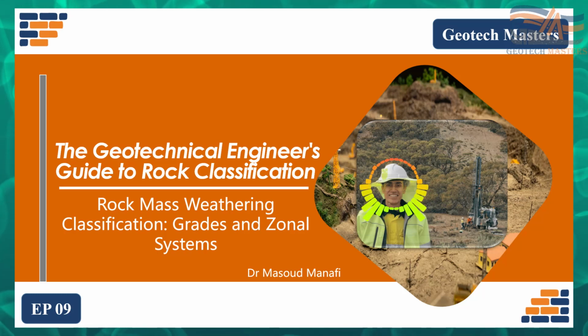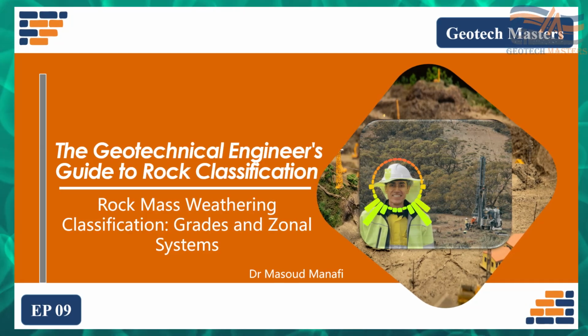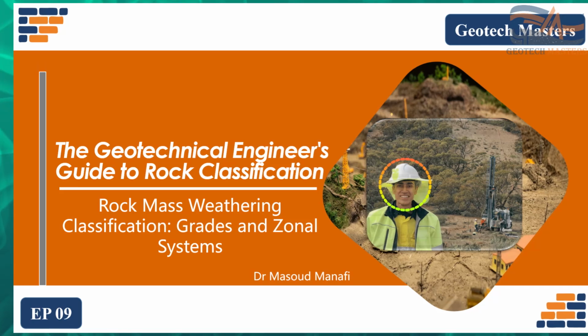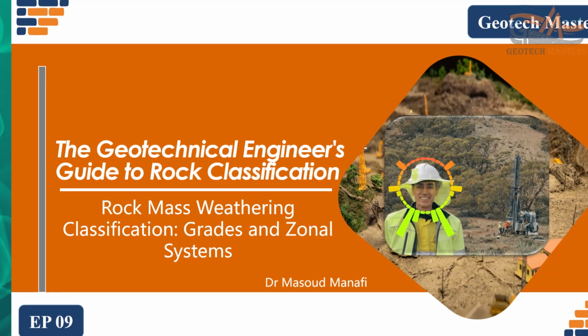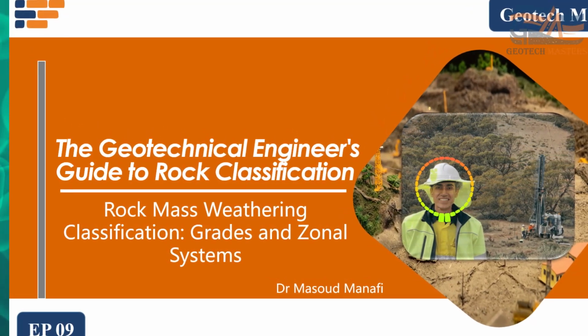Earlier, we looked at the weathering of the small rock piece in our hand. We called that material weathering. But today, we need to look at the bigger picture. We are going to discuss rock mass weathering. Why do we need a separate classification? Because a rock mass is not uniform. You might have strong, fresh boulders floating in a matrix of weak, decomposed clay.